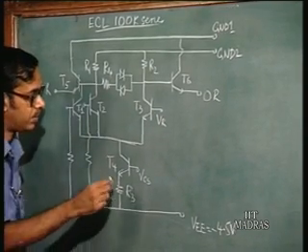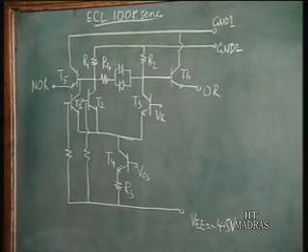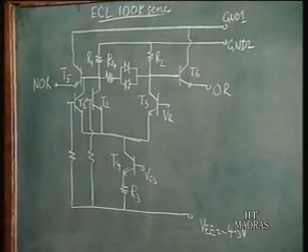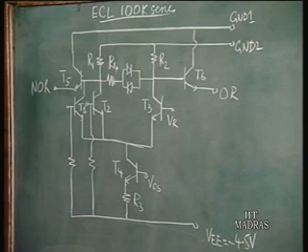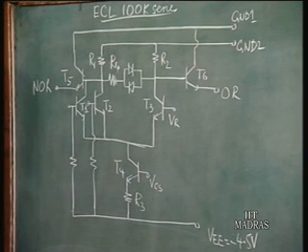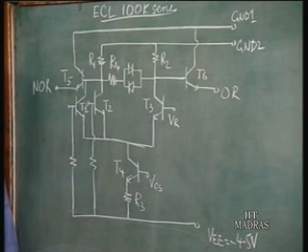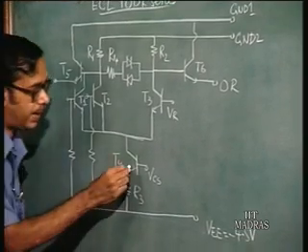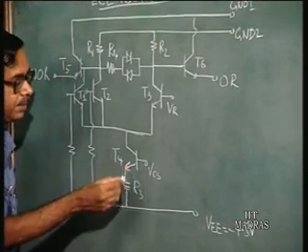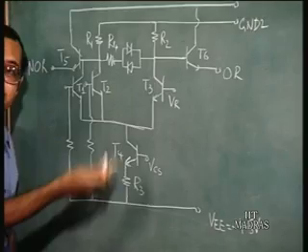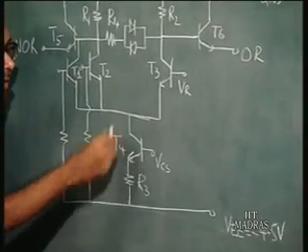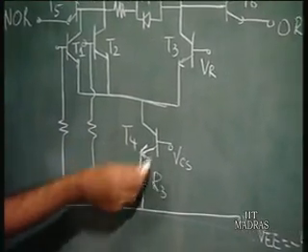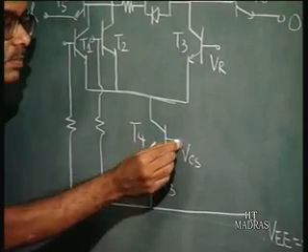You know that in a bipolar junction, in a PN junction, the voltage drop changes with temperature. It reduces by about 1.5 millivolts per degree centigrade or so, or 2. If you assume that, what happens if the temperature rises? Instead of a resistance only as a current source, here you have a proper current source, this is a current mirror type.